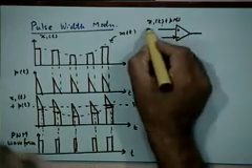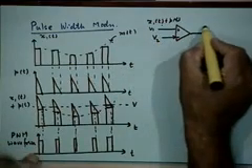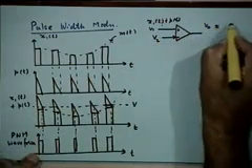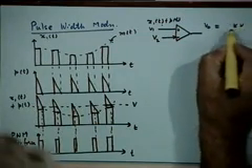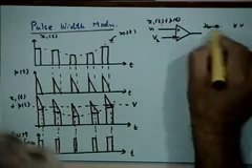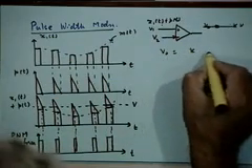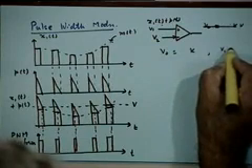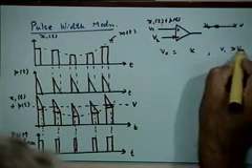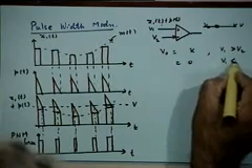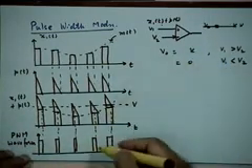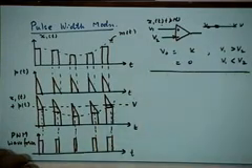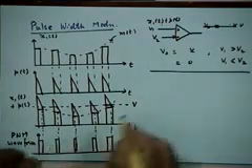Its operation is, suppose you call this V1 and you call this V2, the output voltage V0 is some fixed value, let us say k volts. Let me write it like this: V0 is k for V1 greater than V2, and it is equal to 0 for V1 less than V2. That is what it does, and that is what you have got here. That is what a comparator will do. Okay. What about demodulation?